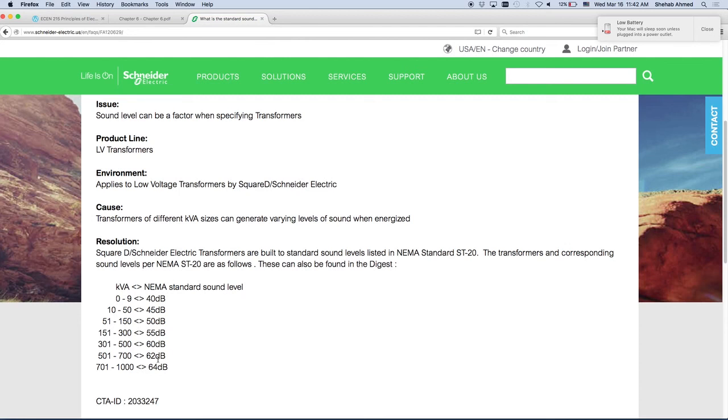It means if you want to attenuate even further, you have to find a way to attenuate the magnitude of this signal if you don't want to hear it. If I don't want to hear this, then at that frequency, I want to make sure that the transfer function of my filter will make the gain minus 100 dB, for example, if I really don't want to hear it. Right? I just wanted to give you an idea of dB and how it relates to noise.